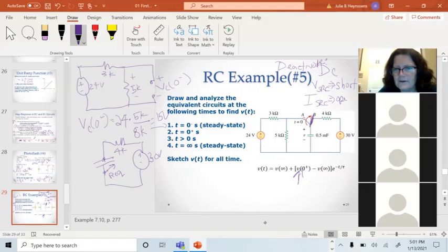So for the Thevenin equivalent, I deactivate any sources that are in there because I don't know the resistance looking into the source. So what I need to do is find REQ looking into a 4K ohm resistor and a shorted out voltage source, and the REQ is now 4K. You'll need to do that like on the homework.